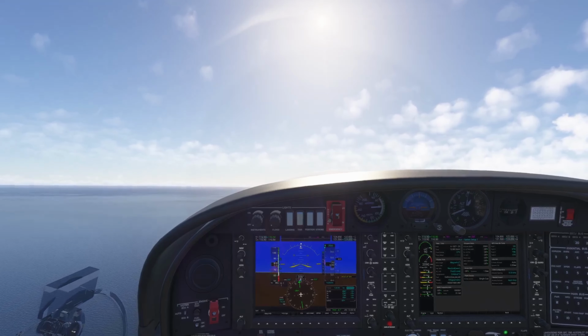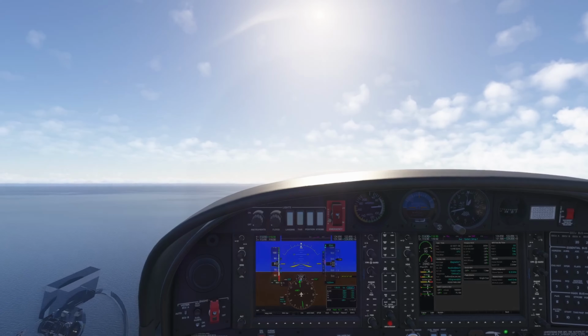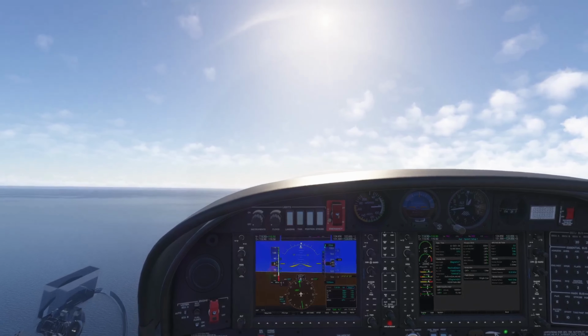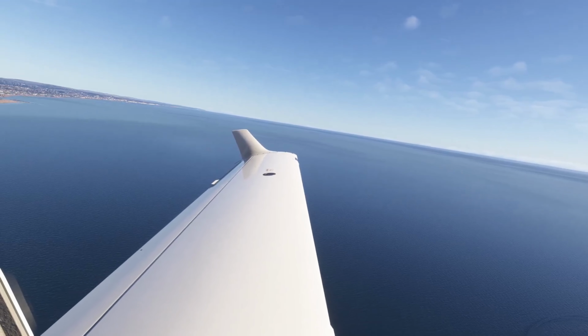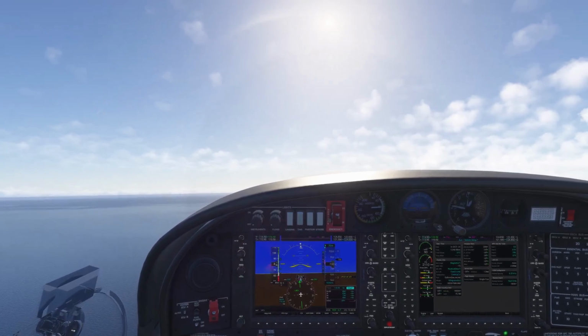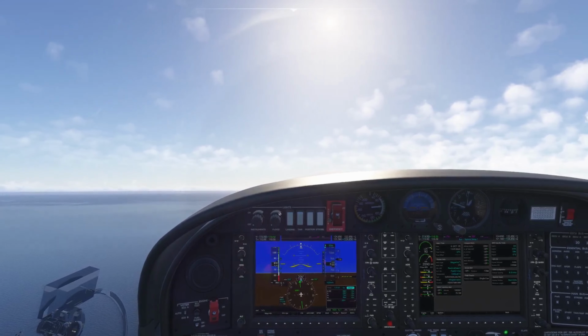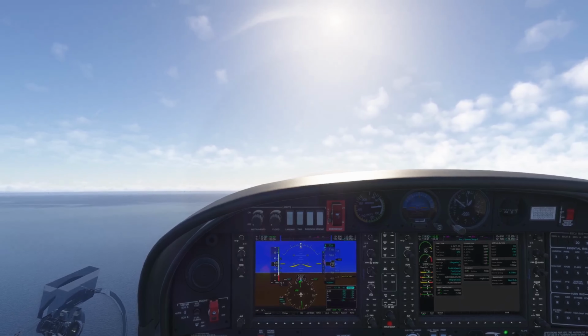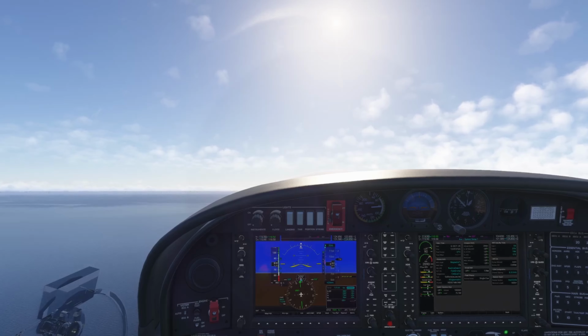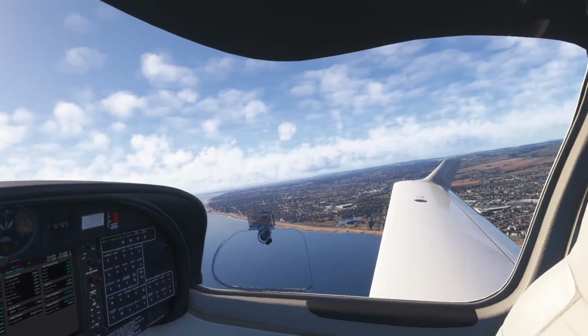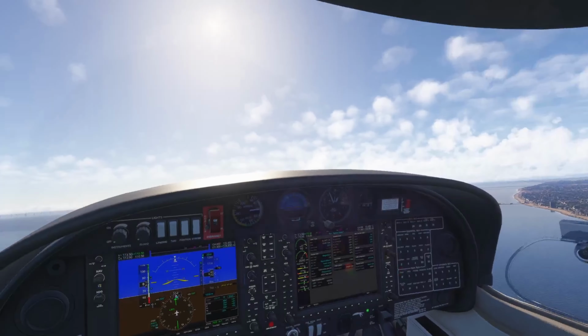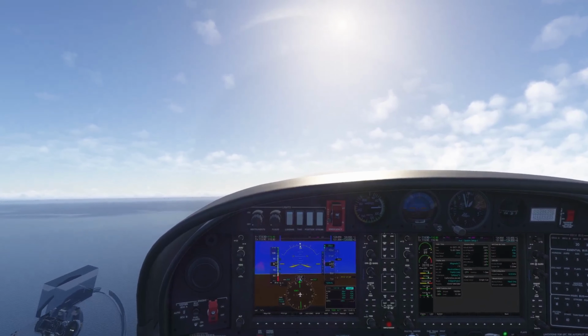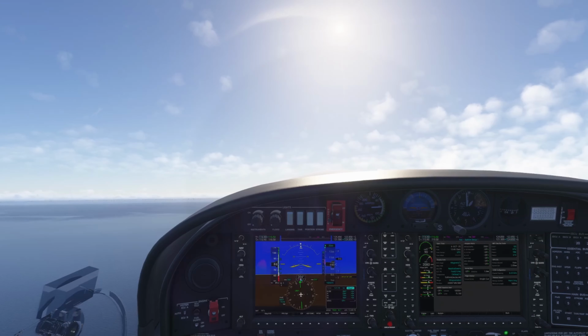So as you can see, we're holding the load at 90%, and that will adjust the RPM. We don't touch the RPM in this aircraft, and we're simply just going to climb on this heading. Make sure we're nicely in trim at 80 knots. So flaps are up, engine T's and P's are in the green. Landing light can come off, and we're in trim at 80. And we're just making small corrections if we need to. We're climbing quite nicely here at 80 knots.